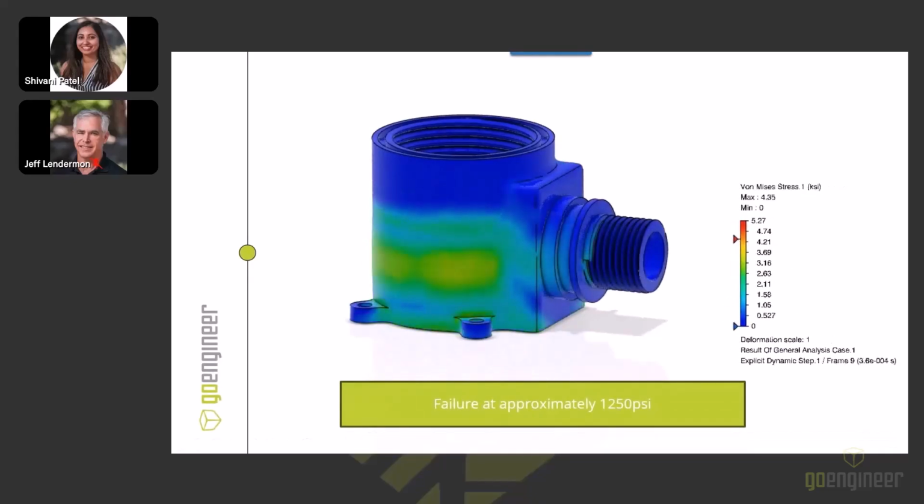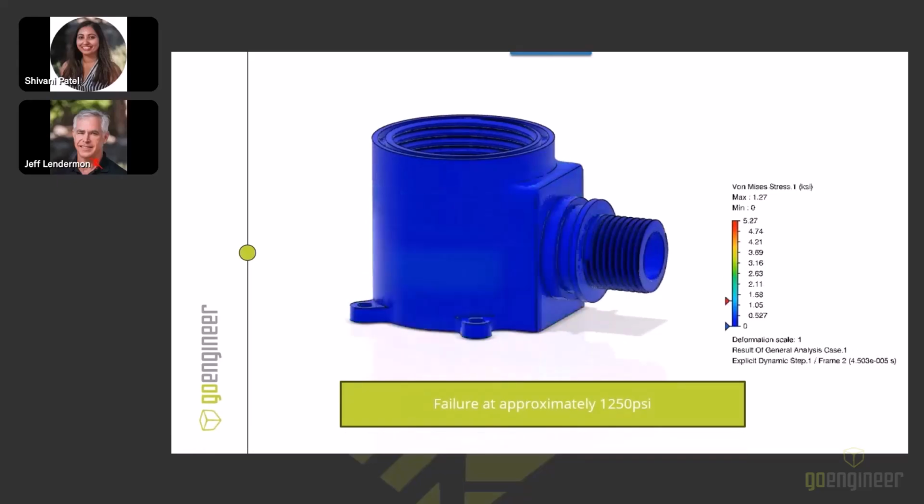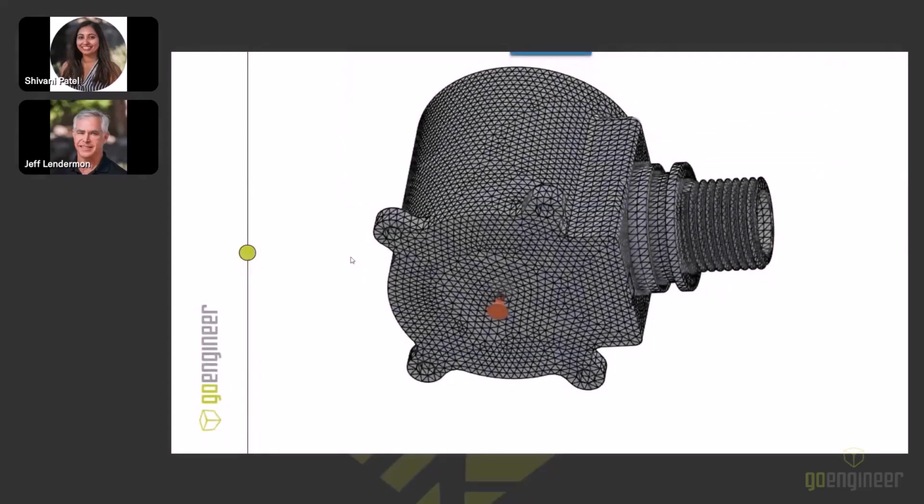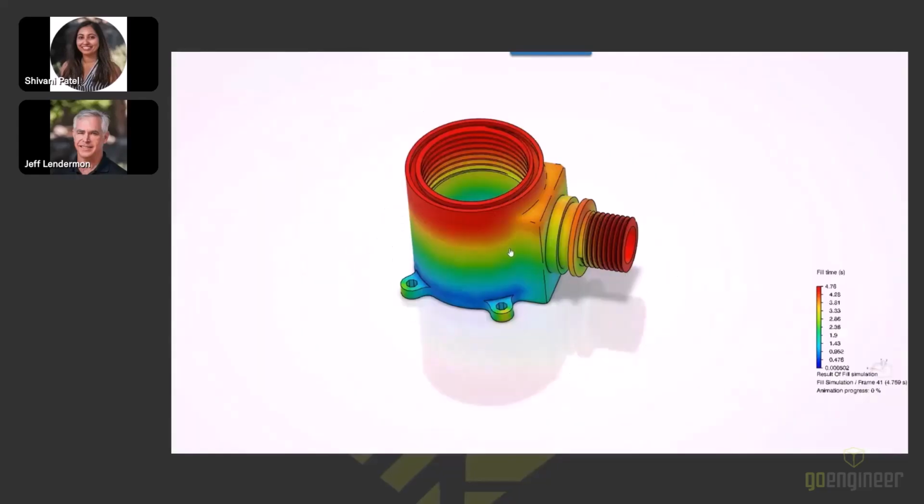So really then the question is, can we find a way to improve this and maybe move the weld line to a better location? And that's really where I would go to Jeff to tell me what a better location would be. So the more obvious answer, in the bottom center of the part, if you're able to gate there, then you're going to get a better fill. And it just depends on how you want to build the mold and everything. But just to show the effect, we want to move our gate location to the bottom center of the part. It's as simple as opening up that study again, starting a new study, picking a new point for the injection location, and then you're running another study. You're going to get more results from the weld line.